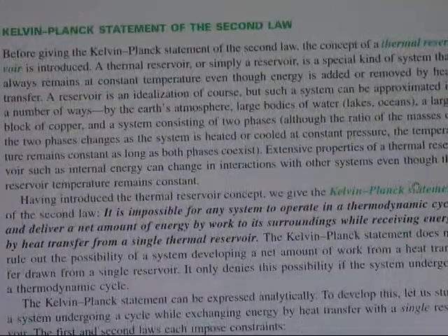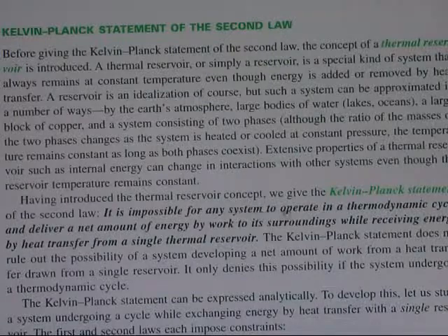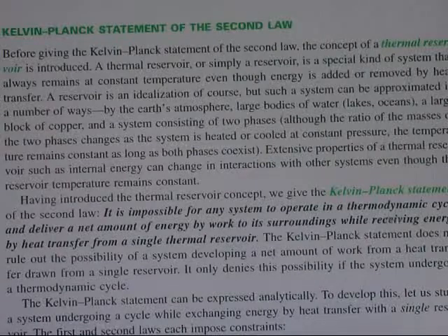So the Kelvin-Planck statement of the second law means that it is impossible for any system to operate in a thermodynamic cycle and deliver a net amount of energy by work to its surroundings while receiving energy by heat transfer from a single thermal reservoir.